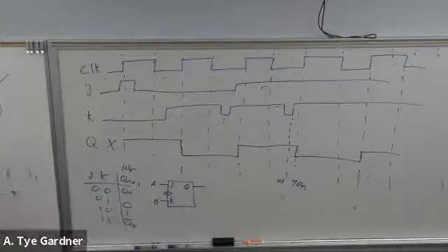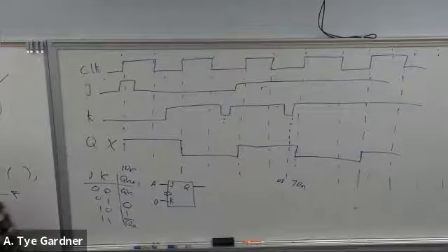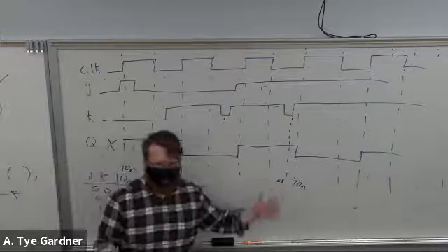What is my minimum? So that'd be another way to ask this. If you had that, and I could ask what is the minimum setup time required for this circuit to function? For this waveform. 2 nanoseconds, yeah. If it's 2 nanoseconds, I just make it and we're fine.